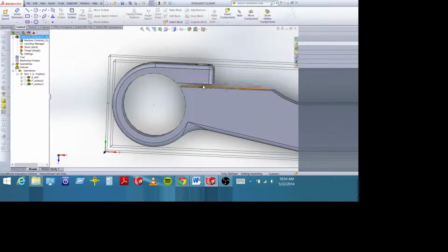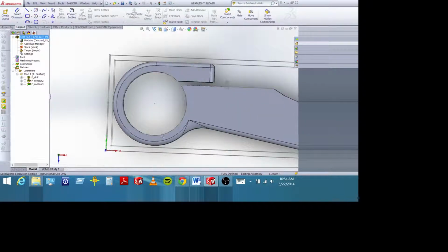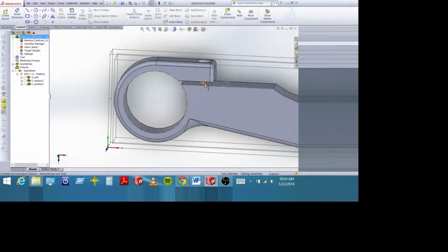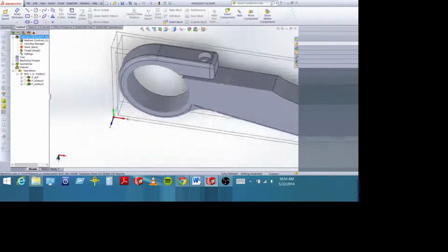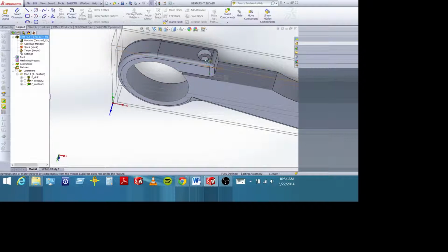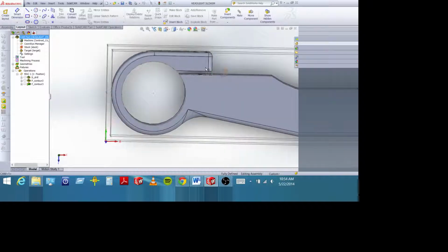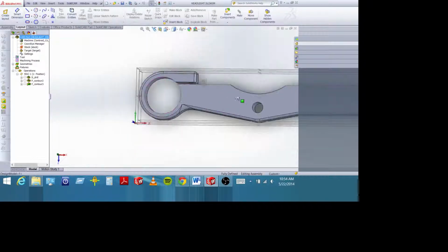the fork goes in here, and then he's got this piece of aluminum that's cantilevered off here with this slot. And then he's got a threaded hole right here and a counterbore hole right here. So he's going to put a screw in here, and it's going to sit flush. And then as he tightens this down, it's going to bend this cantilevered beam down and crimp onto the fork and hold it in place. Okay, so that's the design.